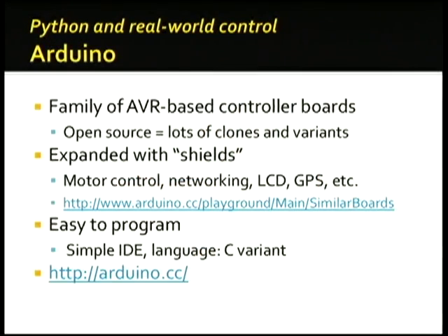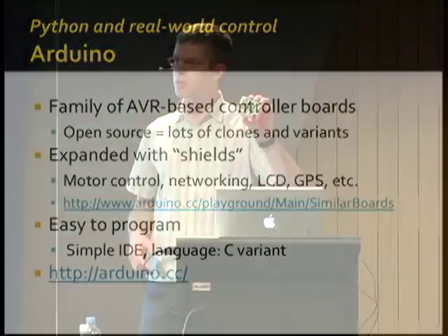If you want to move up a level, the Arduinos have stacks more I/O, and they have lots of nice little interface boards like this that sit on top. So this one's 4 relays. If you wanted to do things like turn on the pool pump, for example, or you want to switch lights on and off, you could have an Arduino coupled into one of these boards that just plugs in on top and do the appropriate safe, responsible mains wiring, and you'd be away.